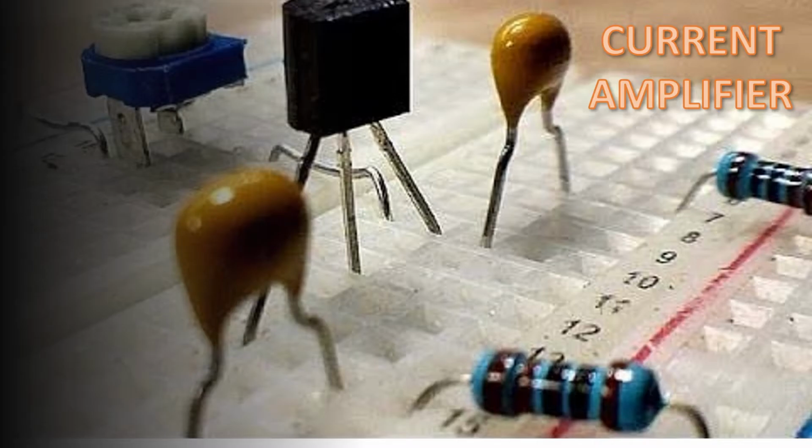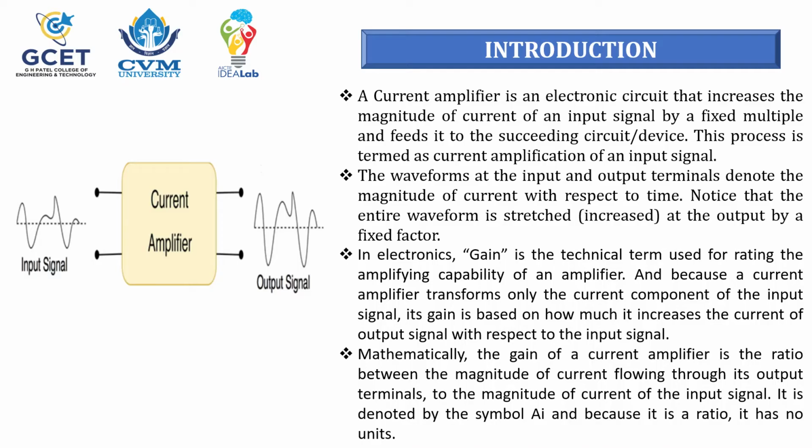A current amplifier. A current amplifier is an electronic circuit that increases the magnitude of current of an input signal by a fixed multiple and fits it to the succeeding circuit. This process is termed as current amplification of an input signal. The waveform at the input and output terminals denote the magnitude of current with respect to time. Notice that the entire waveform is stretched at the output by a fixed factor.